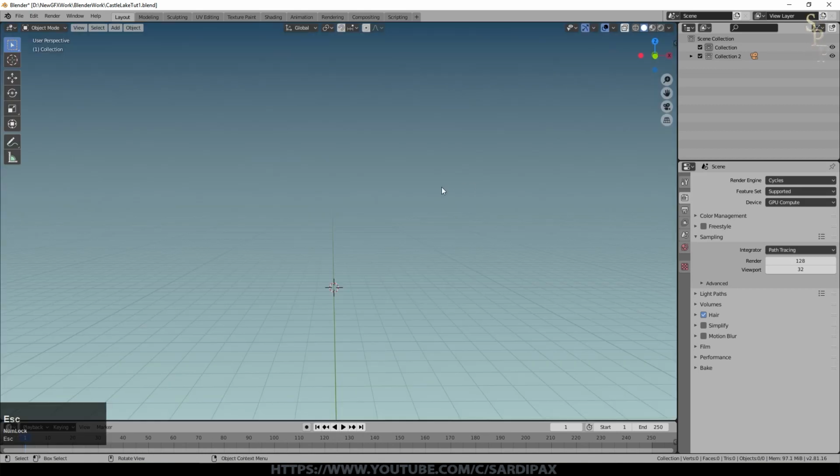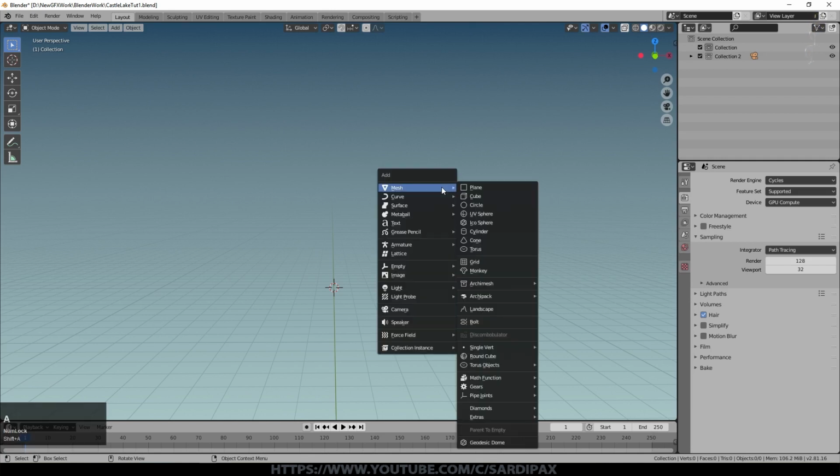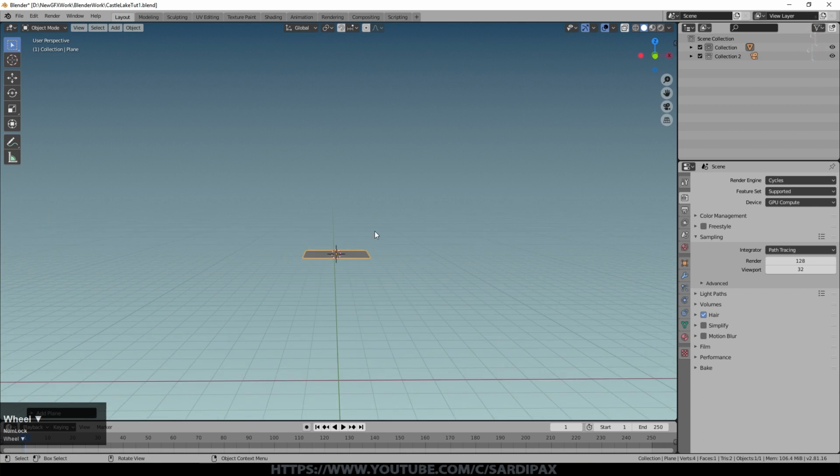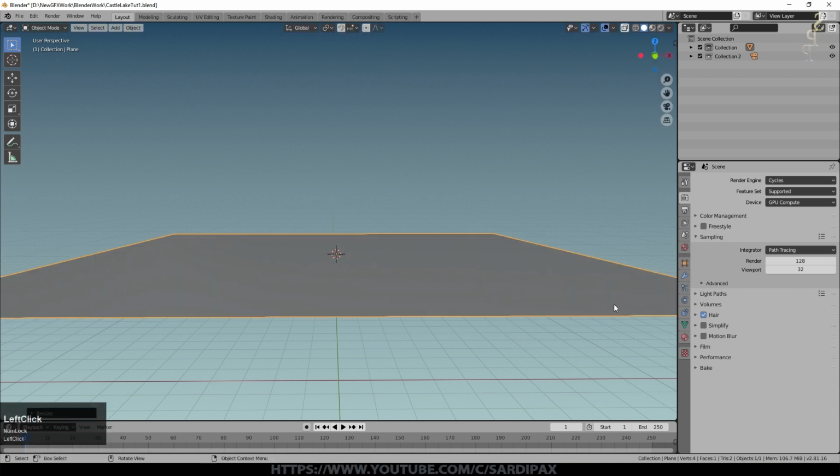So to begin with, we need to create a plane which is going to be our landscape. So we'll just add a plane. Now you can work in real dimensions, and certainly for some scenes that's very important, particularly if you're going to put human-sized characters or machines, things like that in it. I don't worry too much about that when I'm just creating a scene like this, but nevertheless I'll make it a little bigger anyway. And then we'll go into edit mode.